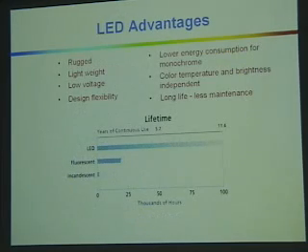Let's talk a little bit further about the LED advantages. It is very rugged, very mechanically stable. It is lightweight. Very thin films are only required. It can be operated at relatively low voltages, 3 to 5 volts. There's flexibility in the design because of the alloying capability that we have. There's lower consumption of energy compared to incandescent or fluorescent lights, and monochrome color, temperature, and brightness are independent, and also there's a very long lifetime.